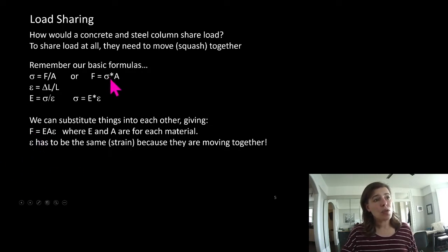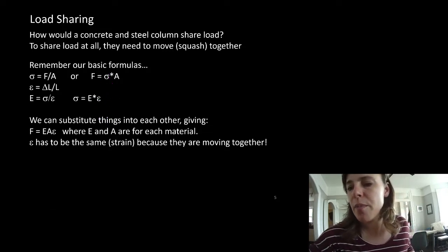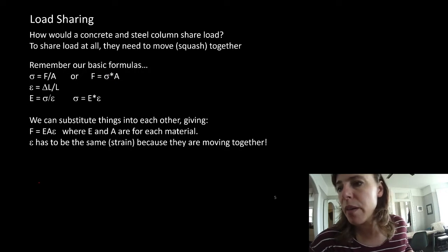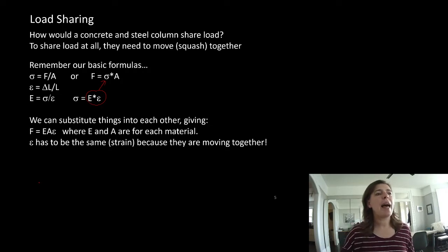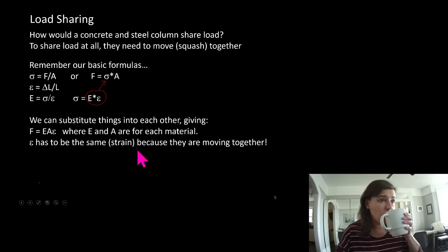Force equals stress times area, and stress can be modulus of elasticity times strain. So let's take this and plug this in here. Let's plug that in there, and we get force equals modulus of elasticity times area times strain, where E and A are for each material, or can be for each material.